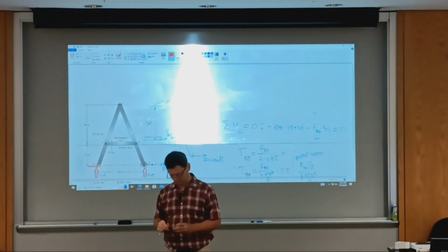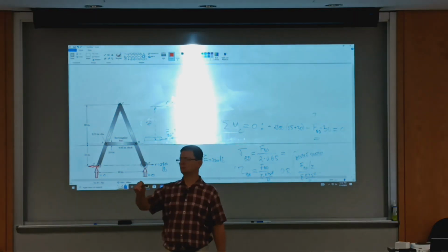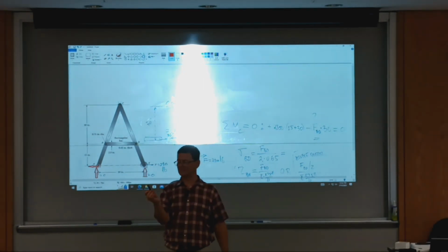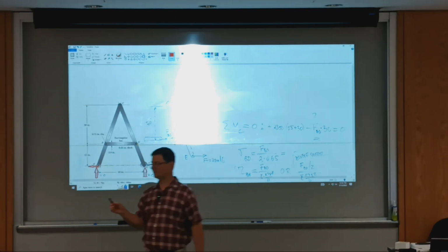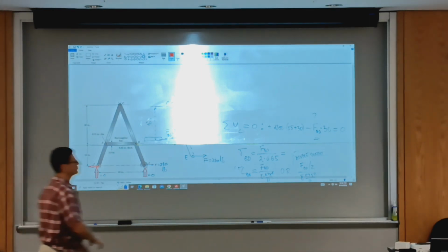I do have here a pin that was used in an assembly, but it doesn't look like it was in double shear. Anyway, you can see the wear. What happened is the load is applied, removed, applied and removed, and as the clearance increases, the wear progresses more because you have more slack to accelerate over.